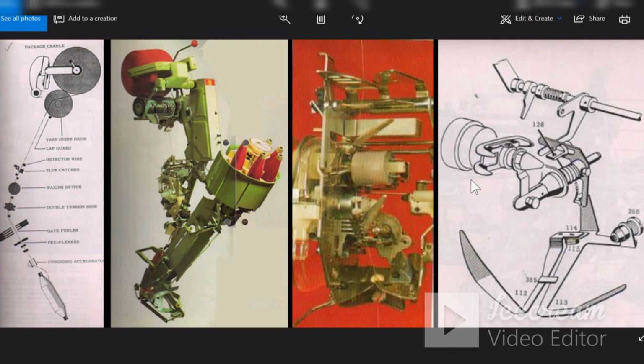So the rotation of the disc by a motor is advantageous in that it does not allow fluff to accumulate. The fluff is driven out because of the centrifugal force. The other advantage of the disc rotation is that it causes even wearing out of the disc. So this shoe is made of a wear resistant material.